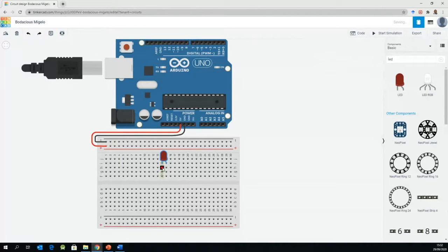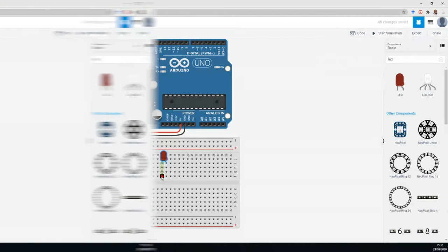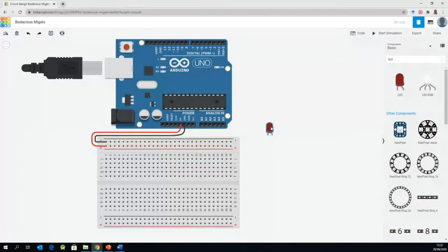Then we do something. Let's try to see how good this quick intro into an LED is. We notice this is the cathode, the shorter one, and the longer one has a bend, which is the anode. So it means the anode goes to positive and the cathode goes to negative. Let's connect this to the positive. I will just do my connection this way.